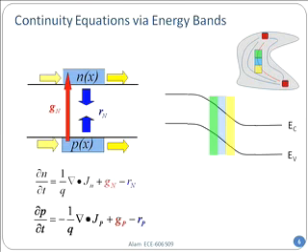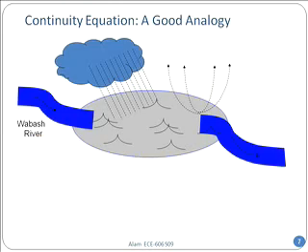Holes have been created, that means electrons have been pumped up, but that does not change the total number of electrons. When something got recombined, an electron was in the conduction band that came down to the valence band. But if you look at the material as a whole, of course, electron and hole number remains the same, no problem. Individual components can change easily, electron and hole number, but not the global number. It's a very important thing to remember.